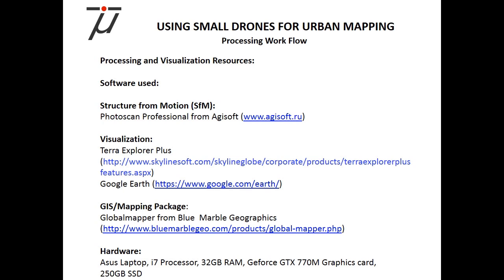So that's the field, the image acquisition side of things. Now the big bottleneck in projects of this kind is the processing. It's big data. We use structure from motion, and I think those of us from the geospatial background should emphasize that when we talk structure from motion, we are not talking classical photogrammetry. There's a lot of arguing going on and misunderstandings because people don't separate these two kinds of approaches clearly enough. I was very glad to see that the colleague from L.L.C did that. So we are not talking about classical photogrammetry here.